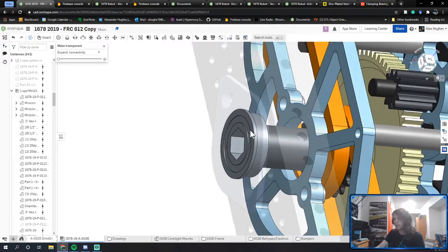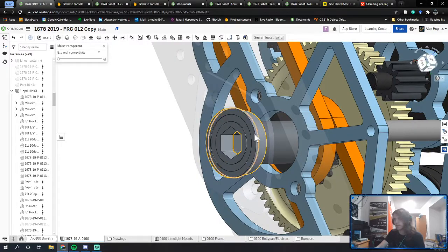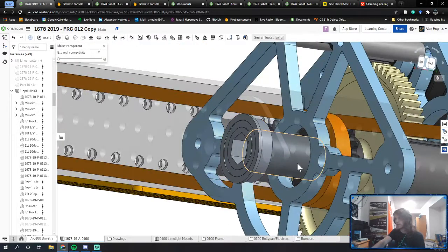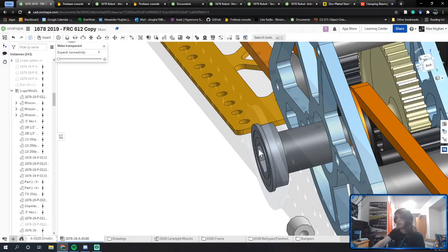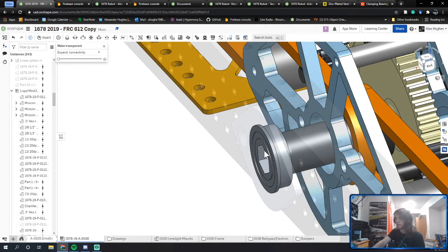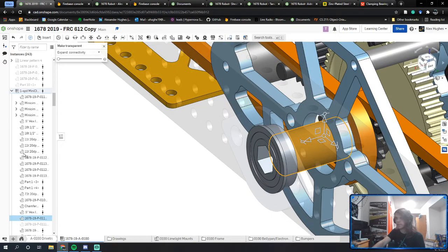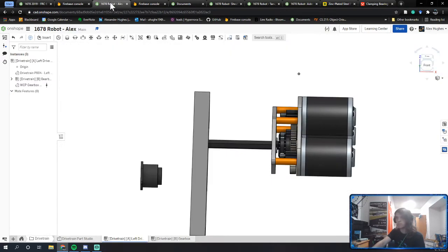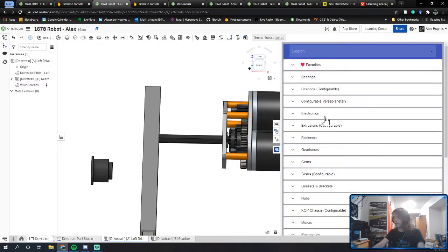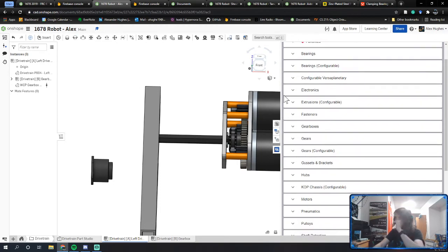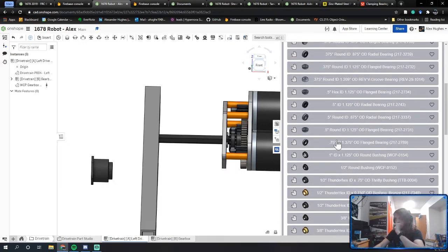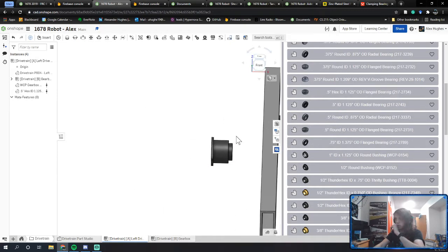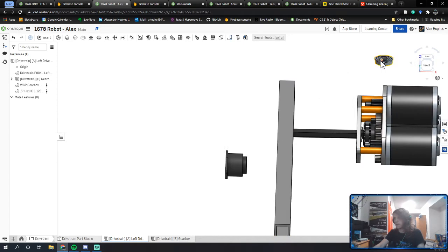I'm going to need one standard flanged half-inch hex bearing. That's going to go inside of the clamp. And then I'm going to need a spacer. That is a custom spacer, so we'll make that here in a second. I'm going to go back into MKCAD and pull a bearing quickly. Bearings, we want the half-inch hex. Half-inch hex, 1 1/8 inch outer diameter flanged bearing. This guy.